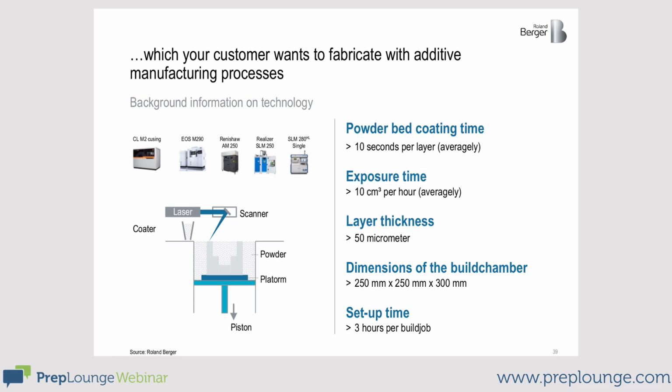When I need big amounts of units or during mass production, the point is to have very fast and productive machines. These machines are usually expensive. For example, during injection molding. That only pays off when I produce numerous units. Here, I don't need any tools, which means I can be relatively profitable with a small number of units as well. The second advantage is that I can melt each layer independently based on my preferences. That enables me to create very complex geometries, which I wasn't able to produce with existing procedures. That's an important aspect to keep in mind.